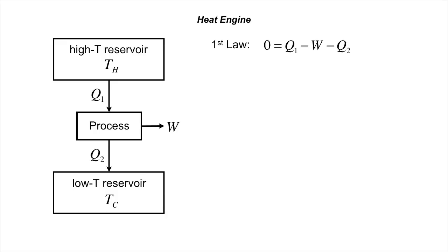However, to do this, we need to be clear about the temperature at the boundaries of our process. In the context here, we'd like to understand all the possible irreversibilities that our process could have. Thus, let's draw our system boundary such that heat entering or exiting our process occurs at temperature TH and TC, respectively. In other words, any temperature gradients that occur as part of the heat transfer to or from equipment in our process is considered part of our process.